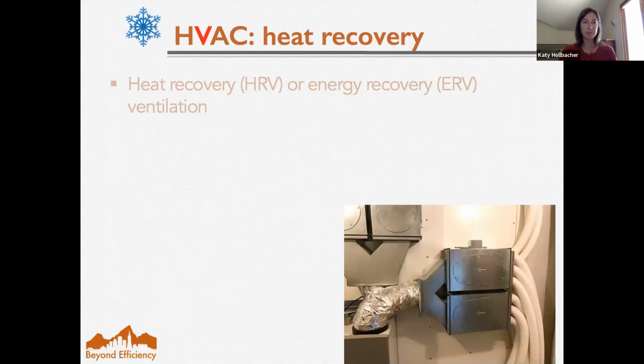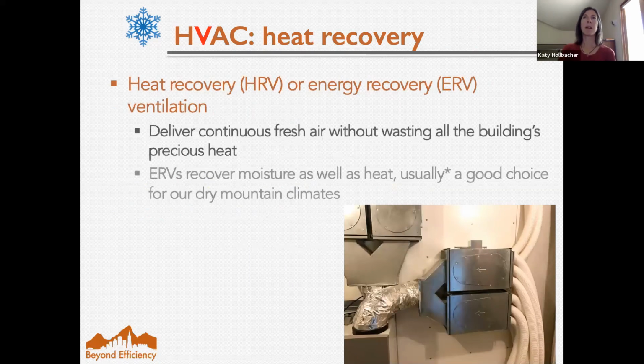So again, we talked about ventilation: build tight, ventilate right. I think using a heat recovery unit or energy recovery, essentially the same thing, it's just that the energy recovery is also helping to recycle moisture, is such an important aspect in these cold climates.